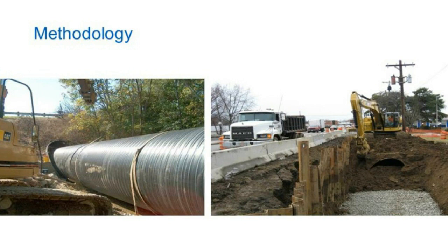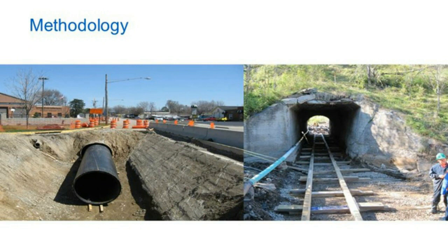In the photo on the left, you can see that the contractor has decided to push the pipes in using the strap attached to his backhoe. In the photo on the right, you can see a contractor has used gravel to create a good level surface for him to work from and be able to join the pipe. In these two photos, you can see how the contractor has decided to use rails far outside the culvert for the ease of joining and pushing in the pipe. These are planning decisions that really should be made prior to beginning your project. And Joe will talk about inserting the rails and some of the reasons for putting rails in further on in this section of the webinar.